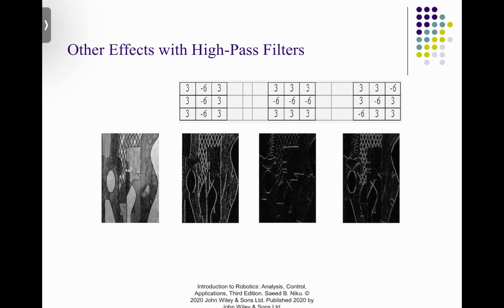What you have is the intensity of the pixels varying at a high magnitude. So this is basically high frequency content. Otherwise, say you have a horizontal line. This is one pixel, this is the other pixel, this is the third pixel. These three pixels are next to each other. The intensities are not varying quickly. This means this is low frequency content.